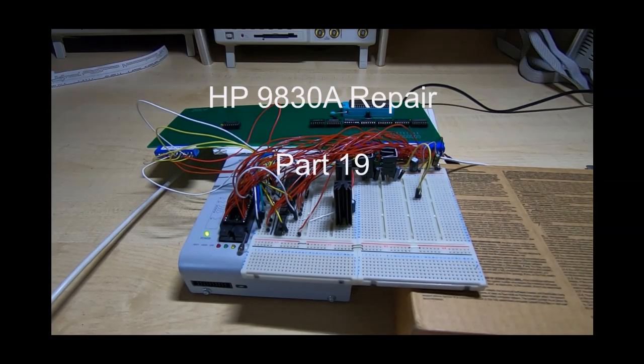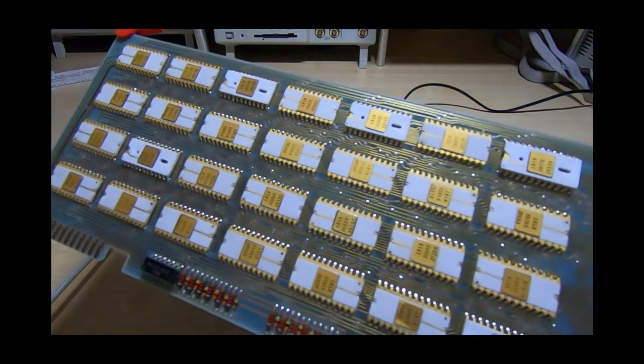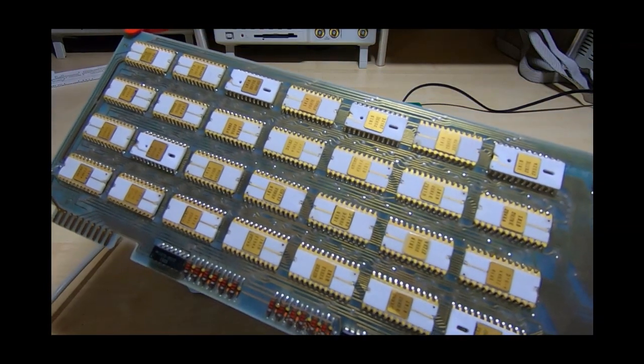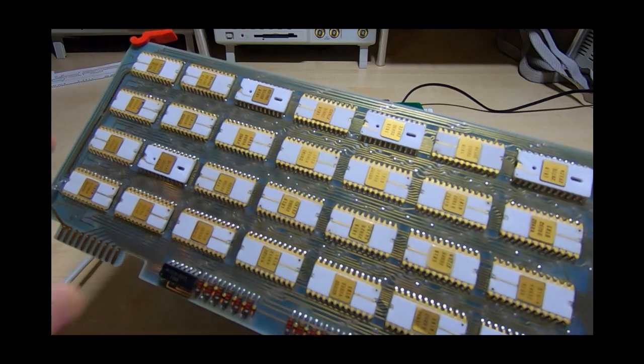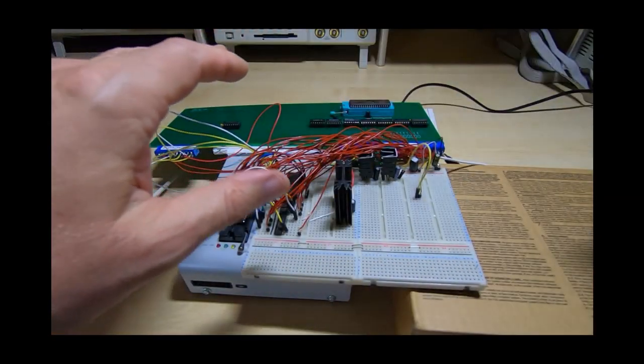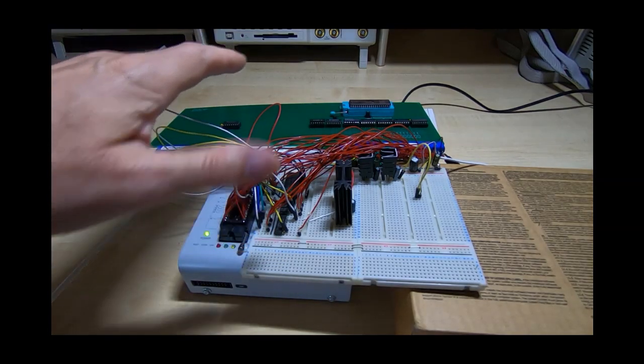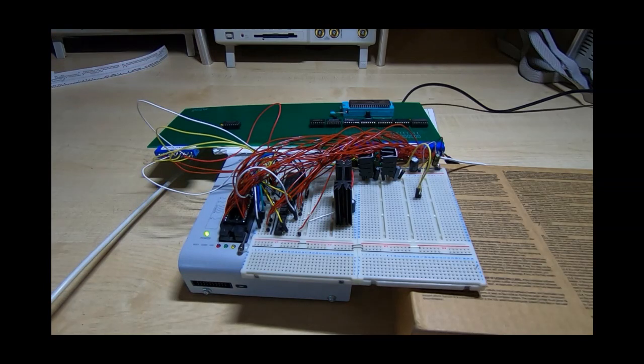This is part 19 in a series of videos in which I'm attempting to repair an HP9830A desktop calculator. In the previous videos I've carried out various repairs and got as far as identifying that a remaining fault was in the ROMs on the main ROM card. And of course I couldn't get the ROMs, so I took the route of designing a replacement ROM card using a standard EEPROM. I've gone as far now as programming the code into the EEPROM.